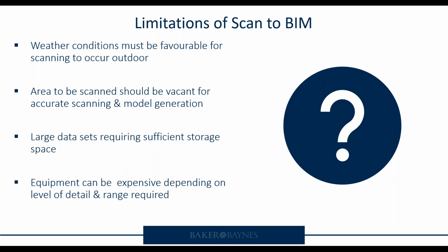It's also very important to ensure that you get the right scanner for the right application. For example, you would not use a scanner like the BLK360, which is predominantly used for interiors, to scan the plant. You would need something with a much finer accuracy, millimeter or micrometer if you can get them, that's catered to capturing plant at the level of detail that you need. So you need to bear that in mind.